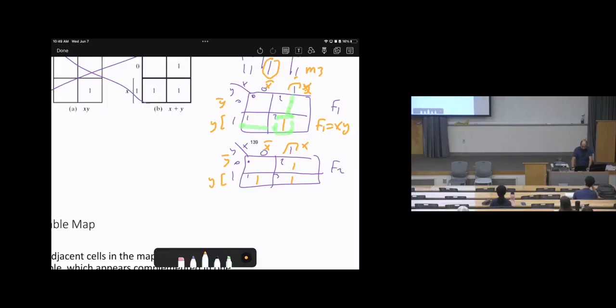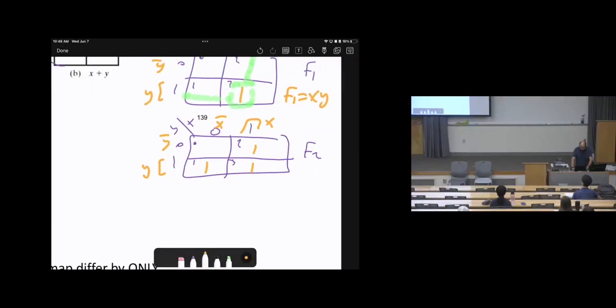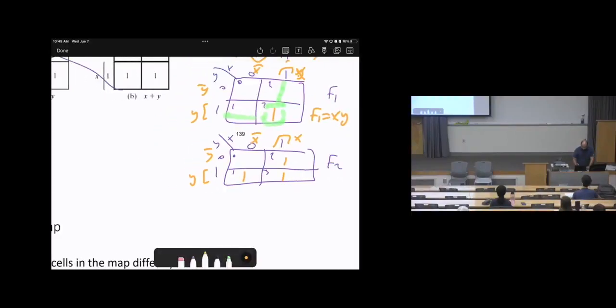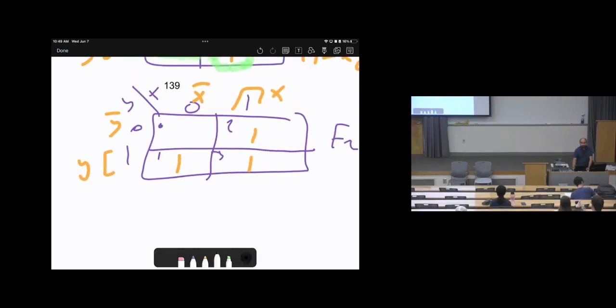Okay. Now, how to make the simplification using the other function? In Karnaugh maps, in order to do the simplification, we can look at two adjacent blocks and combine them as one variable. Here, we can group 2 or group 4. So you start first with group 4. Can you group all of these 4 together? No, because we have only 3. We cannot group this because we have a missing variable here, right?